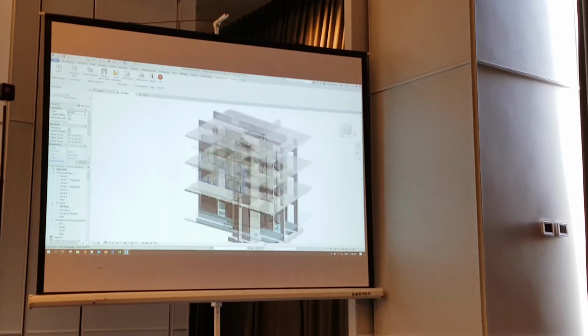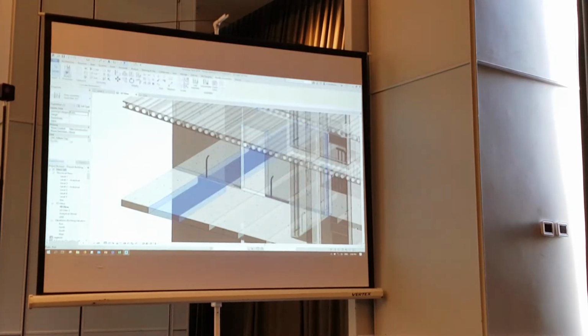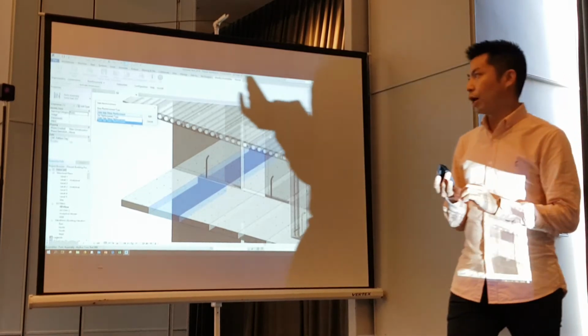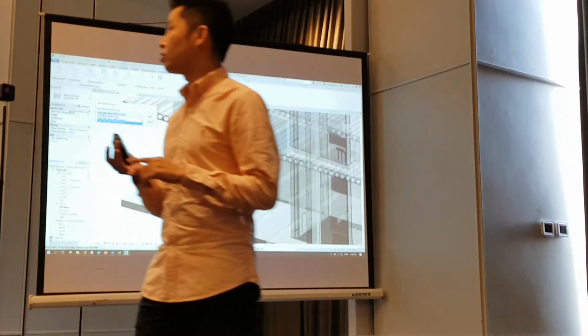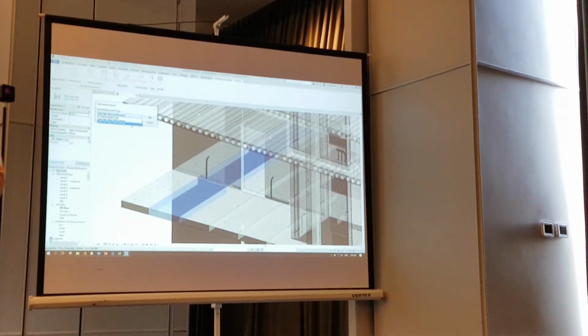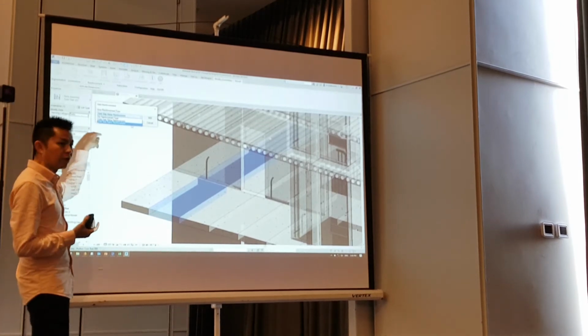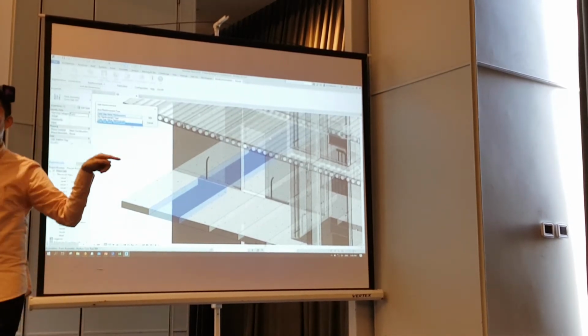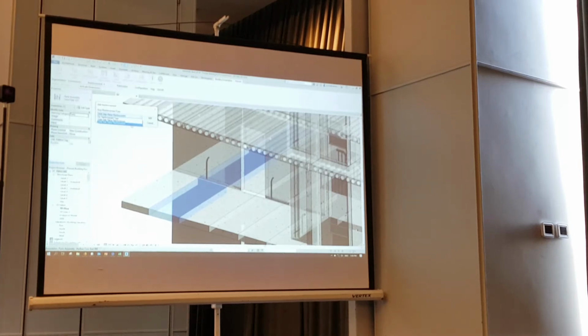So let's say I pick this one, go to the precast tab and click on reinforcement. Once I click on it, it asks you to choose whether it is a solid slab rebar reinforcement or a fabric reinforcement. Where do we get these selections from? It is from the configuration tab inside there, so you can go back there to make changes.